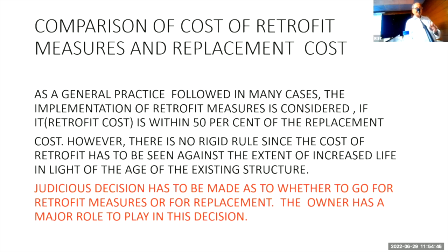there is no rigid rule since the cost of retrofit has to be seen against the extent of increased life. That increased life you have to judge in light of the age of the existing structure. So I have given in red ink in my slide, a judicious decision has to be made as to whether to go for retrofit measures or for replacement. The owner has a major role to play in this respect.